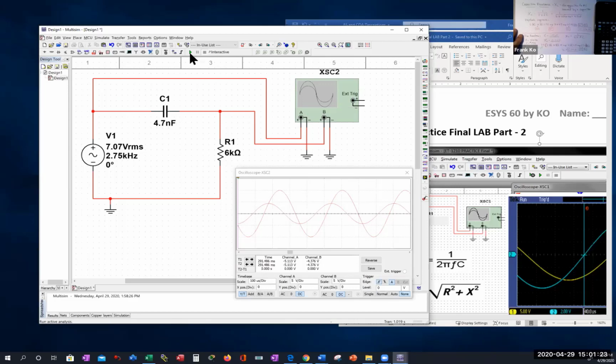be able to hit play, click the oscope in order to get the display, and then adjust the oscope for time base in order for the waveforms to become separated. Make sure that these are both in the same scale. You hit stop, and then adjust your cursor left and right, because the last thing you want is something like this, where you don't fill up your screen with the waveform. If you have the oscope in the run mode, like this, everything's dancing around.